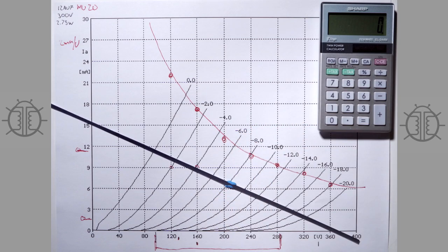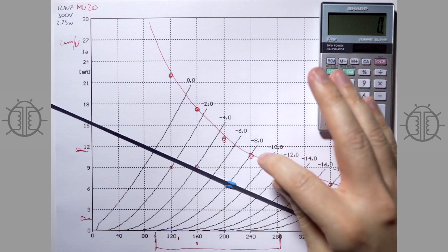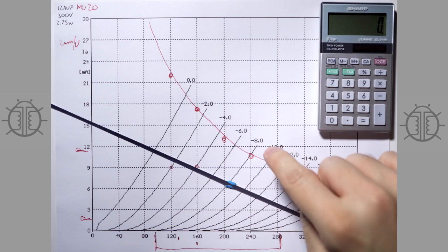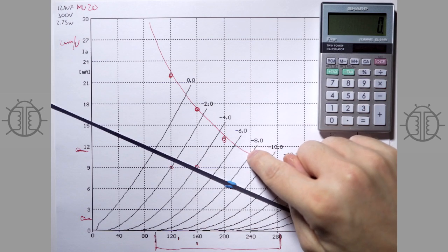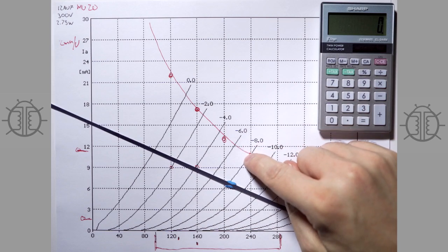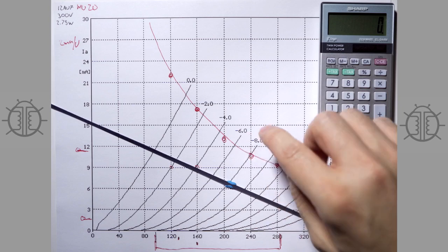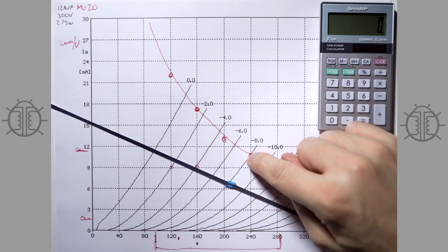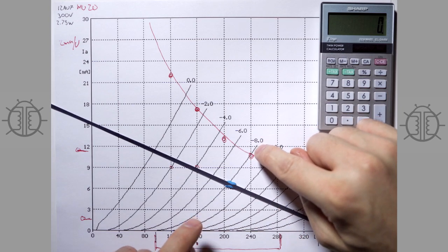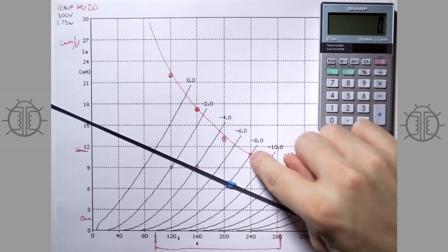To ask what the impedance is is to ask how much current you have to supply to change the voltage of the plate 1 volt. And so what you look at is, let's say you've got a -8 between your cathode and your grid. And so let's say I wanted to change the plate voltage by 40 volts here.